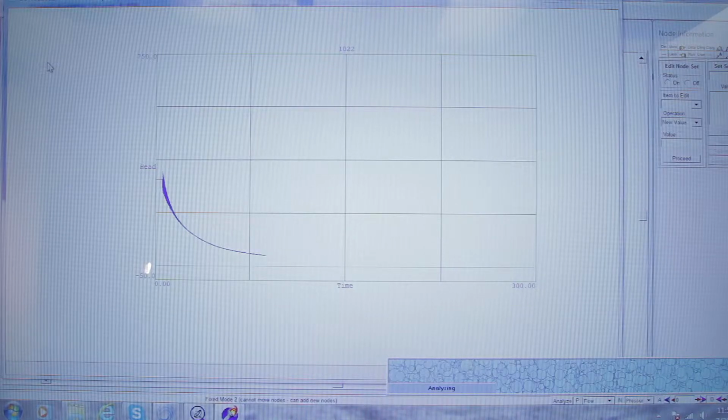And remember, we're pumping down 7 miles. At the end of the line, our minimum operating pressure, as I said, was 25 psi. But again, we want to try to keep that positive. We want to keep the whole line positive, and we don't want this negative wave oscillating back and forth.